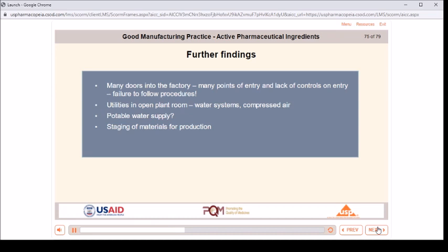Two, utilities were housed in a plant area that was ventilated via slatted windows that did not have any glass, only wire grills. Beta-lactam residues were found in the compressed air feed and around the purified water and WFI storage units. These were functionally closed systems, but they were opened up for maintenance and periodic inspections.